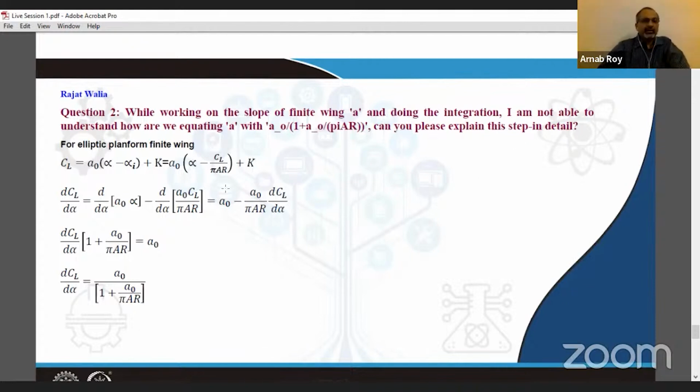Well, we have tried doing that, and how we do it is by integrating the equation that we just left behind for the airfoil case. If you integrate that, you will come up with an integration constant K. We leave it as it is, and we continue to assume that it's an elliptic wing, so that we have a nice expression for alpha I, and that remains constant all through your span.